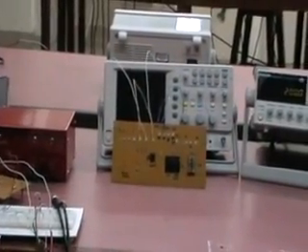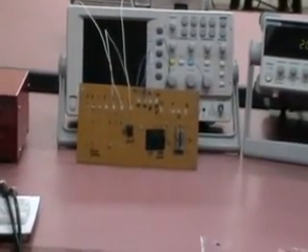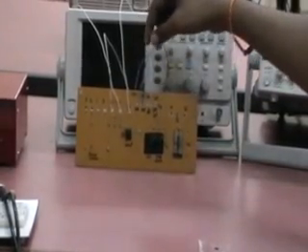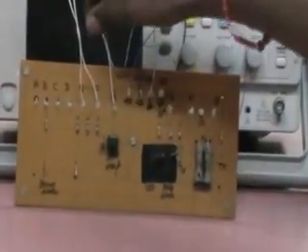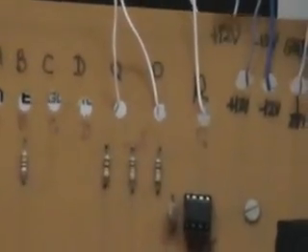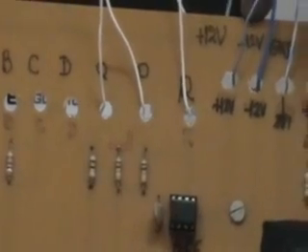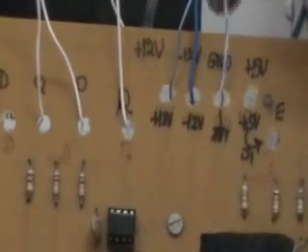The differential amplifier circuit is already made on a printed circuit board with P and Q as its input and R as its output. As you can see, this is the PCB, printed circuit board. This is the differential amplifier. In this, Q and P are two inputs and R is the output. And the power supplies, DC power supplies are given across these wires, 12 volts, minus 12 volts and ground.